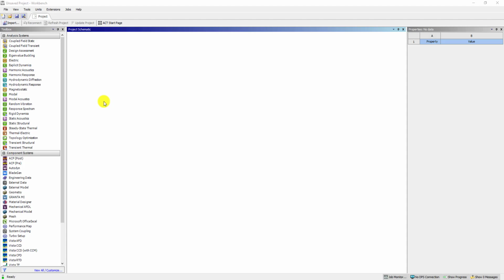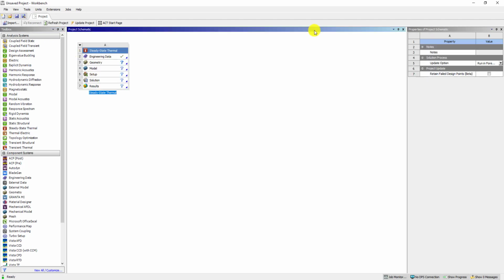So let's do this composite wall problem in ANSYS. And this is the Workbench interface. You know how to open it from the past sessions. Instead of taking a static structural, we'll take a steady state thermal. So as soon as we drag and drop a steady state thermal to the project schematic, ANSYS knows that it has to solve K into T equals Q equations.